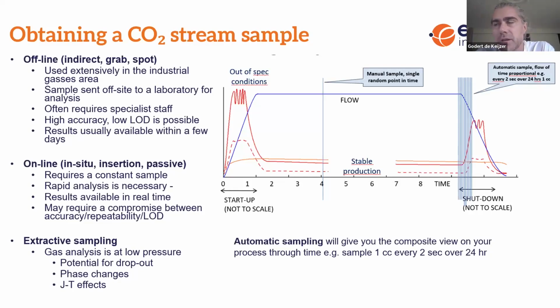the pressure and temperature that you can measure it under in the online analysis has a couple of drawbacks or risks of actually changing the actual composition of the gas or the fluid that you look at. The advantage of the online analysis is that it really allows you to continuously monitor the stream, and if it changes, then make interventions. It's important to recognize that even though it's fast, there is still a cycle time dependent on the type of equipment you choose and the specific fabricator that provides it. Okay, so let's move on to the next slide.